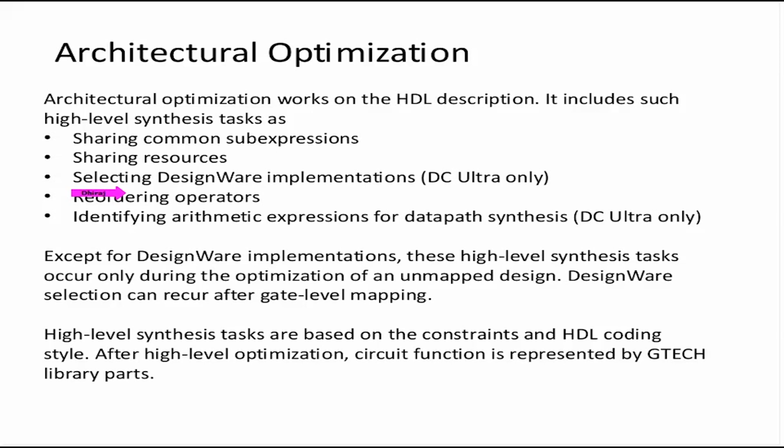Reordering of operations to make sure that the area is minimal. Identifying arithmetic expression for data path synthesis. Now, a few of these things, like selecting designer implementations and identifying arithmetic expressions for data path synthesis, these options are available only in DC Ultra.